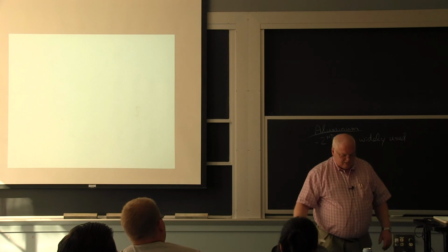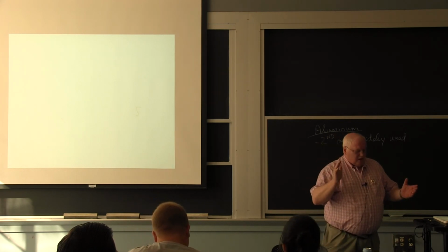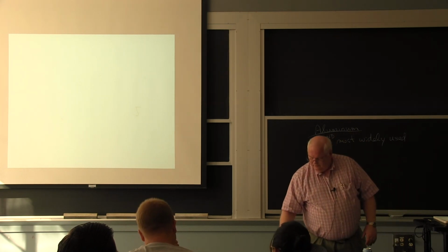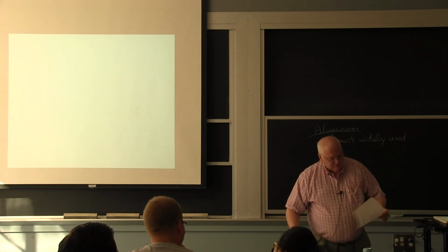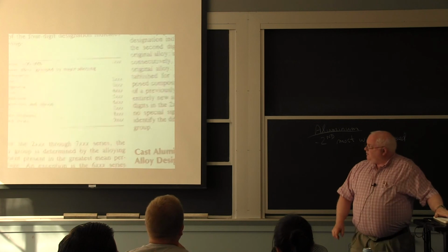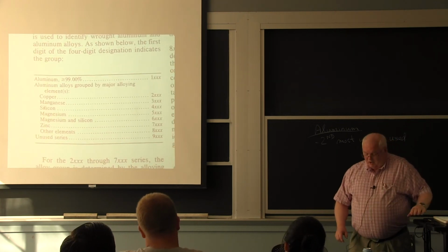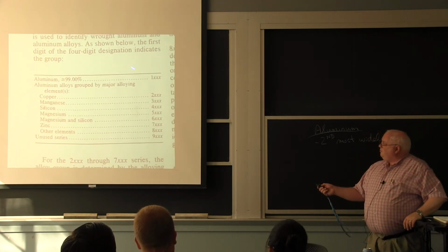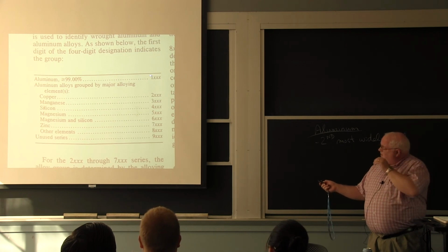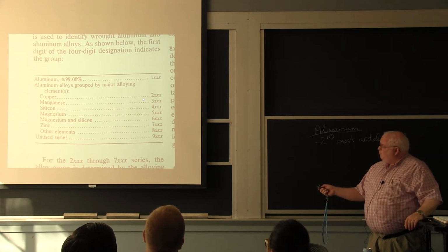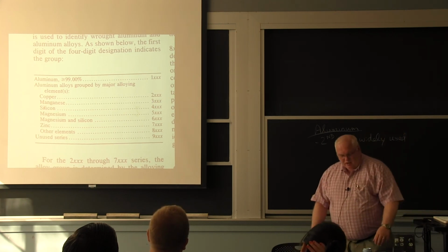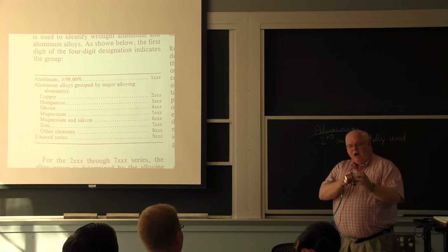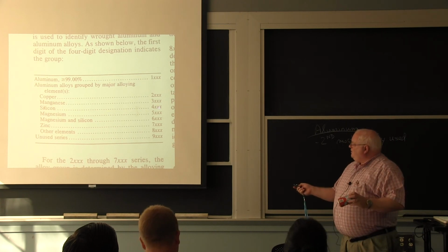Aluminum, what did I want to say about aluminum? Oh, well, I can talk about aluminum lithium alloys. Actually, I was going to talk about some of the other alloy designations. So the other alloy designations here: copper, 3000 series are manganese. They're basically like the 1000 series, but they have about 1% manganese and gives them some strength. So the can stock, the body of the can, is typically 3003 or 3004 alloy.